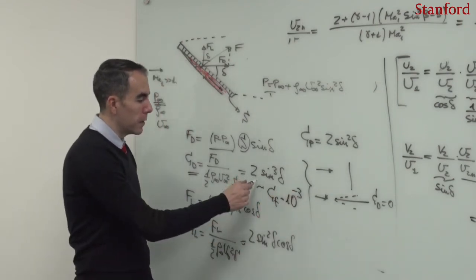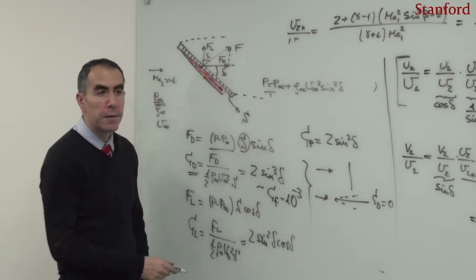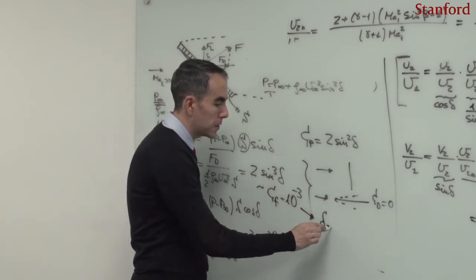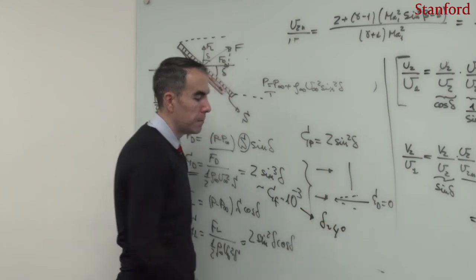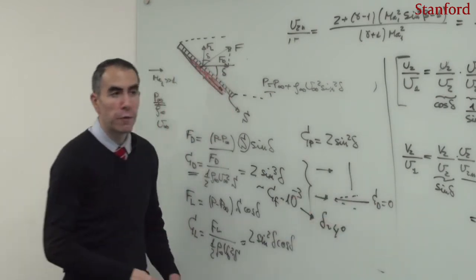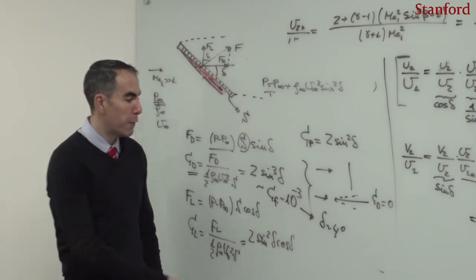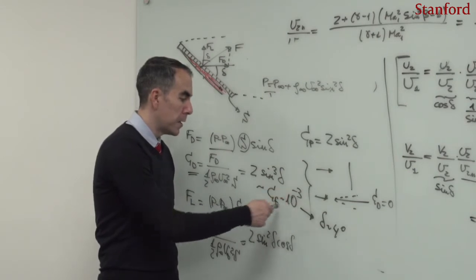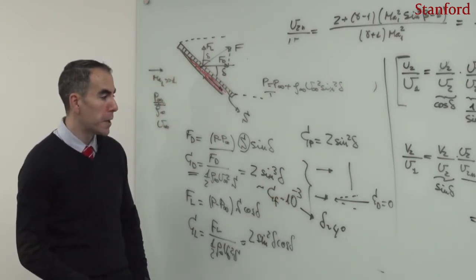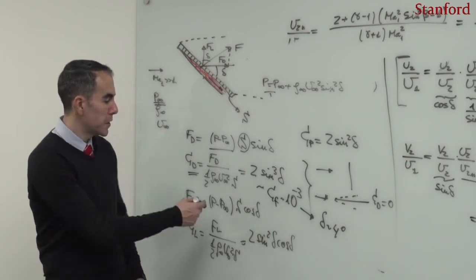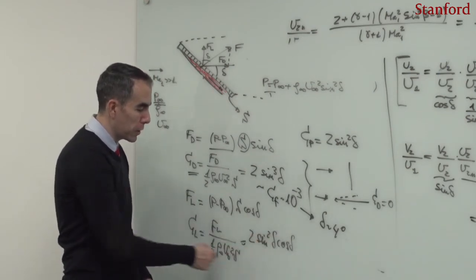So if I obtain from here delta, you can calculate that this delta will become 4 degrees. So that is to say that as soon as the inclination of the plate is about 4 degrees or less, then you may expect viscous effects to come into play here, which are not considered in any of this. Well, so for instance, for the same reason, if I look at the lift force